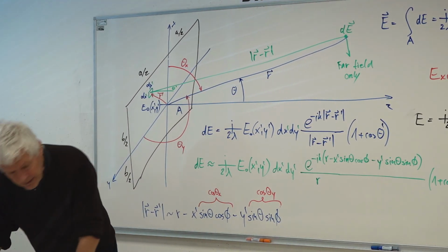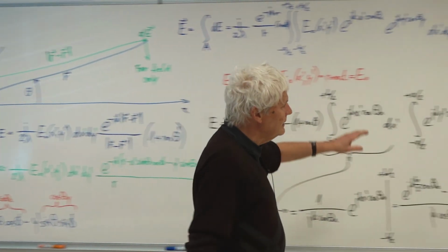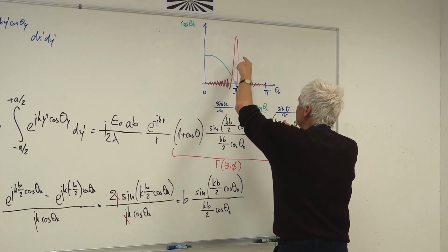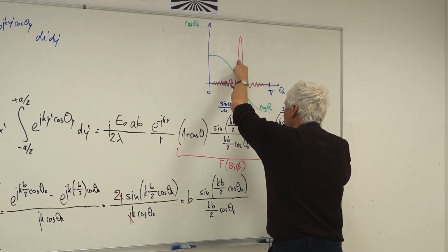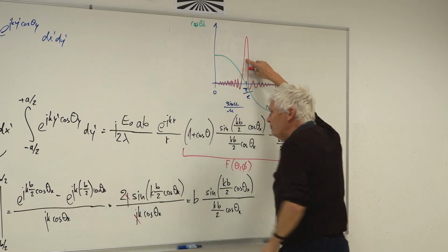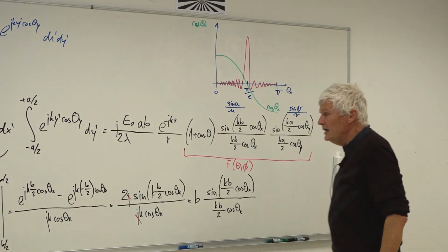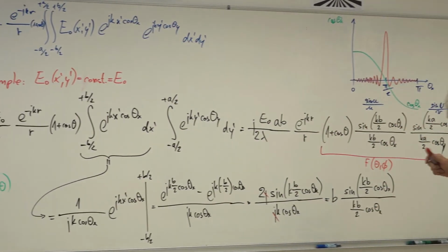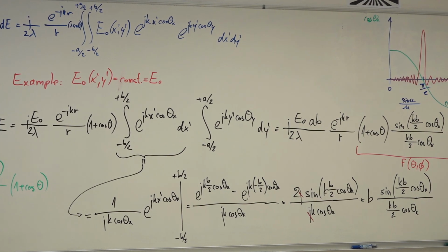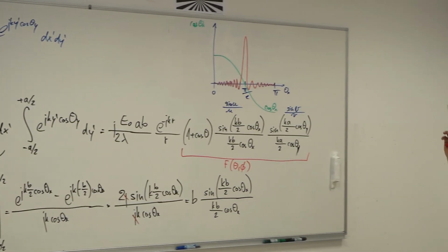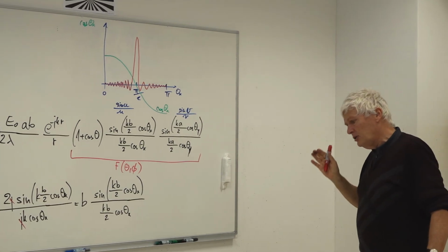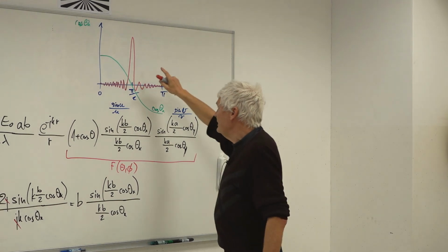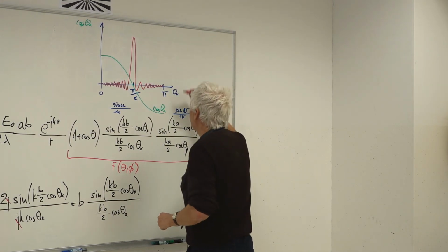So I can get arbitrary directive antennas in this case. Choosing large B and large A, I can shrink my radiation patterns so as to have a very narrow beam radiated out of such an antenna, if I have, of course, constant illumination of the aperture, and we'll try to do that on many occasions later on. In this course, we'll try to get the best possible illumination, possibly quite constant illumination. So in this way, I can improve the directivity.